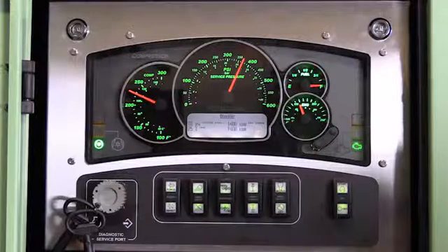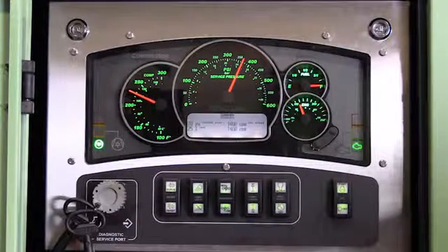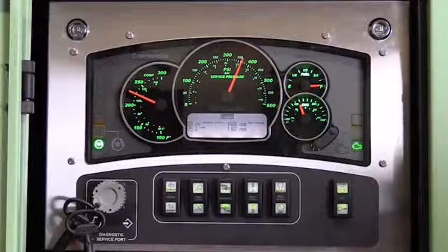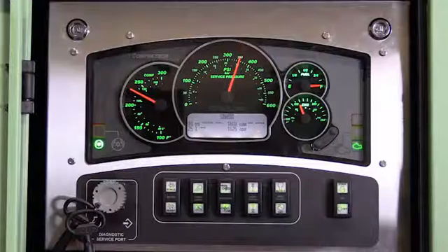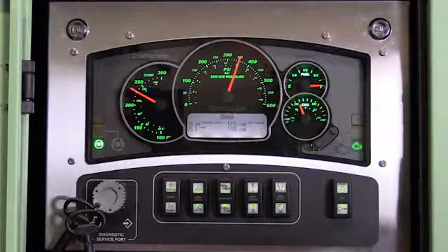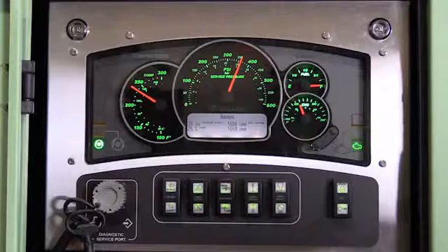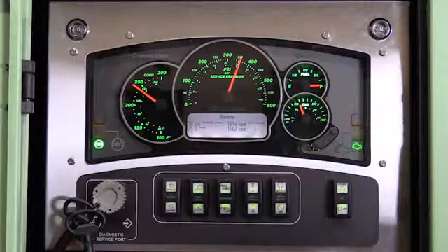During regeneration, the HEST lamp, high exhaust system temperature, on the controller screen should be lit. If for some reason the emissions module is not automatically engaged, regeneration can be achieved manually by holding the Regen switch in the force position on the controller for 15 seconds. This will manually force the regeneration process and soot levels between 15 and 105%.